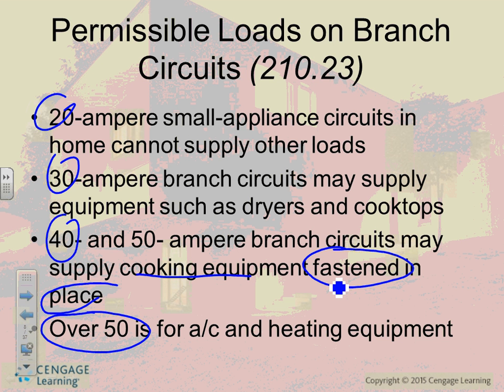Are there any limits on the size of a branch circuit that I can do? No. Can I pull a 4,000 amp branch circuit? Yes. Typically it doesn't happen. You can pull, guys, equipment that can draw 1,000 amp. That's not unheard of, a 1,000 amp branch circuit going to a piece of equipment in industrial. So imagine 1,000 amp, not a panel, just one piece of equipment consuming it. Imagine the service. So there's no limitation on how high you can go in amps on the branch circuits.